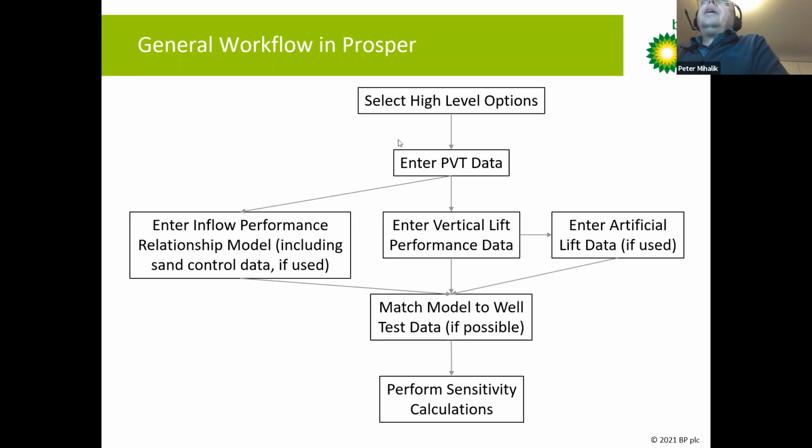And included in the IPR modeling, you can include sand control modeling if you want to model that explicitly as well. You then move to matching the model to well test data, if you have well test data, to make your model as accurate as possible. If you're trying to model a well that may not be drilled yet, then obviously you don't have that available to you. You just do the best you can.